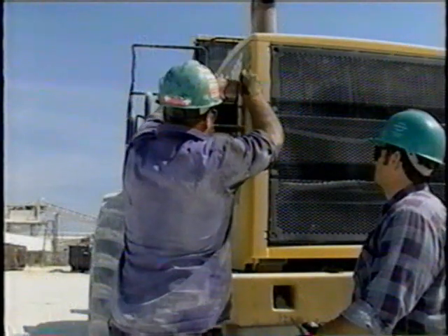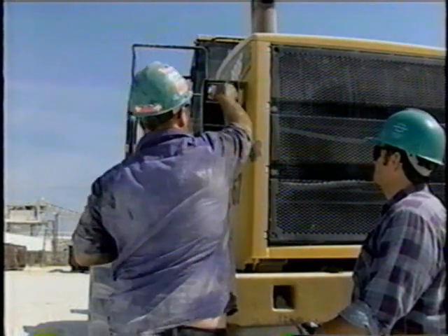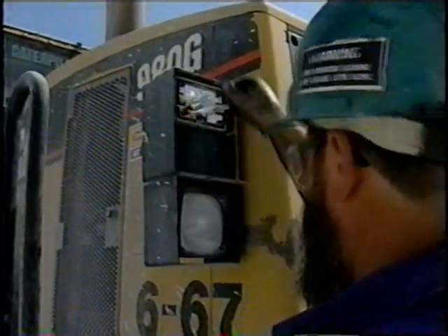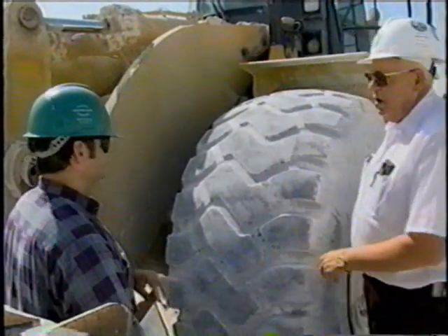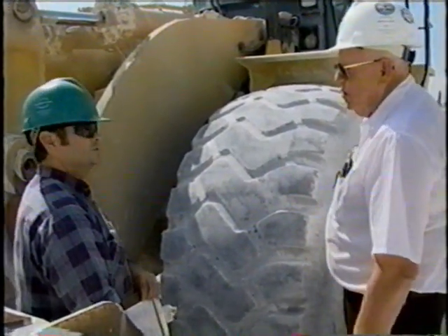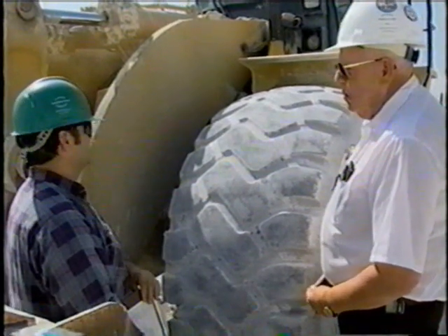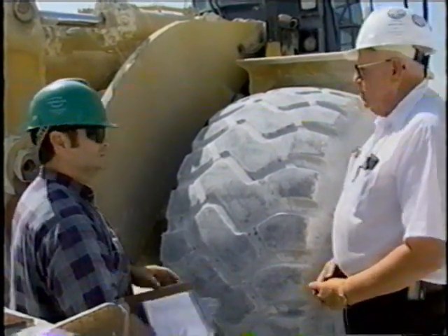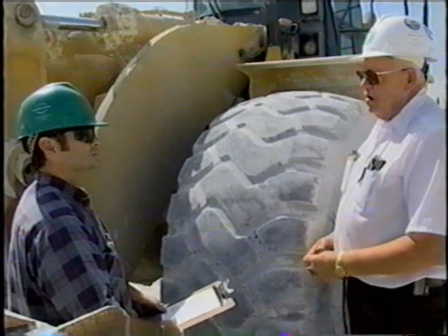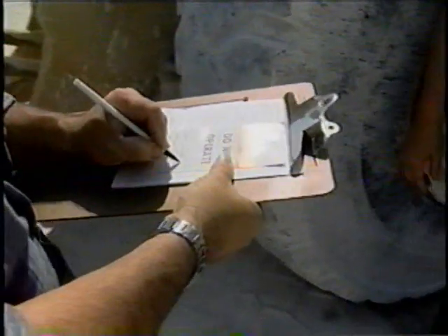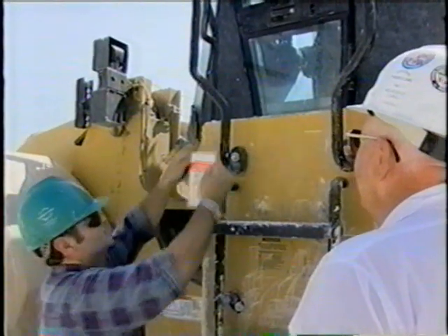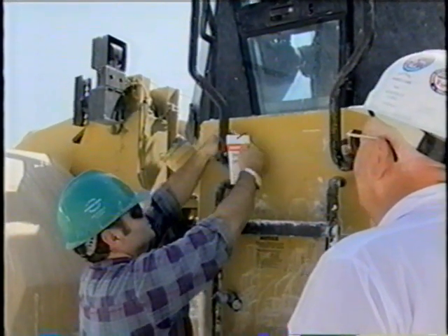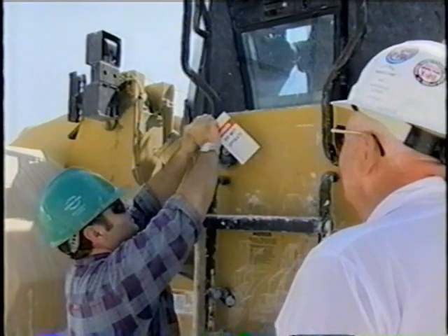Second, defects on any equipment, machinery, and tools that affect safety shall be corrected in a timely manner to prevent the creation of hazards to persons. Third, when defects make continued operation hazardous to persons, the defective items, including self-propelled mobile equipment, shall be taken out of service and placed in a designated area posted for that purpose, or a tag or other effective methods of marking the defective items shall be used to prohibit further use until the defects are corrected.